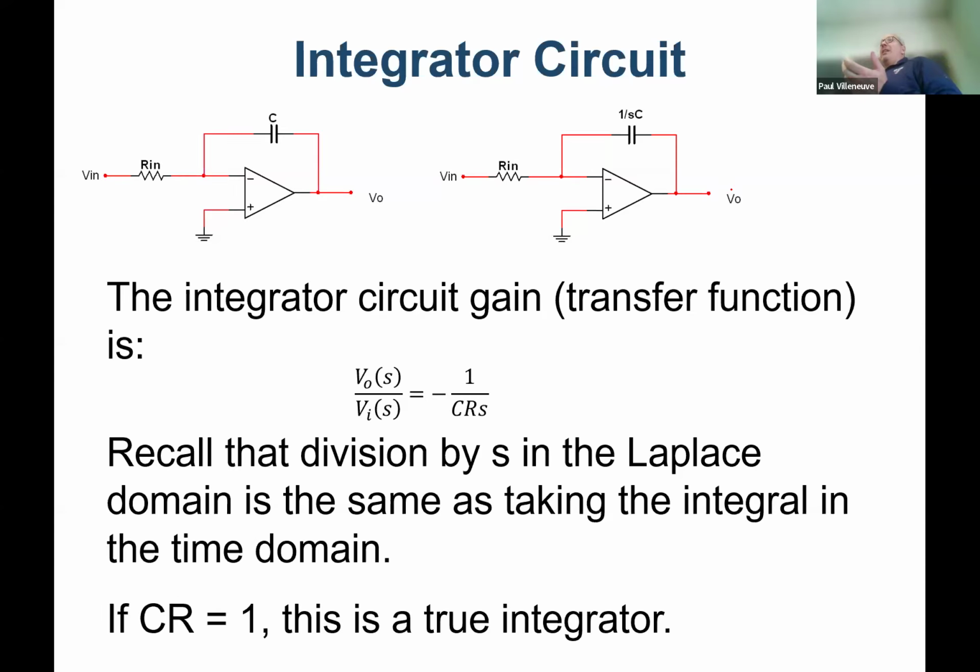A long length of pipe in a hydraulic system is modeled as an inductor and a resistor, right? Because depending on the size of the pipe, it'll add some resistance to the flow. But if it's a really giant pipe, it might not add much resistance. But if it's got a small orifice or something like that, where it's actually restricting the flow, then you can get that. A deliberately placed orifice would be like a resistor. It's exactly like a resistor. Because an orifice is trying to limit the flow of water, resist the flow of water.